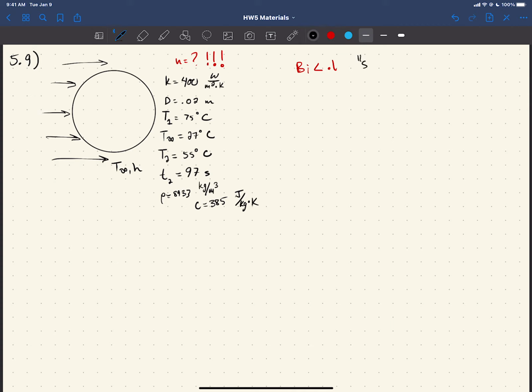That's what space-wise isothermal tells you. How did I know that? Well, that comes back to that discussion I was having before, where the premise behind these problems is that a Biot number less than 0.1 indicates that you can assume it's space-wise isothermal, and therefore temperature is only a function of time, which then allows us to find some analytic solutions.